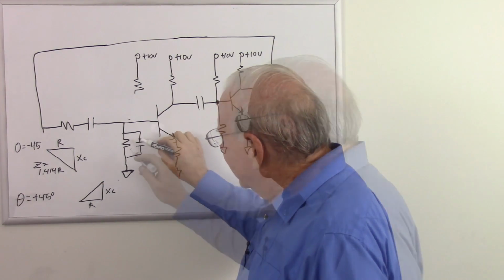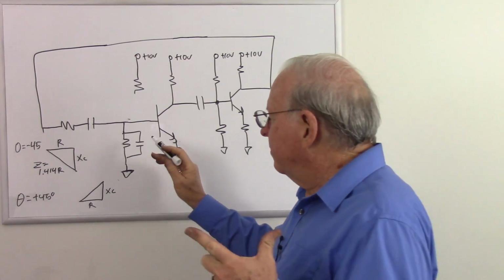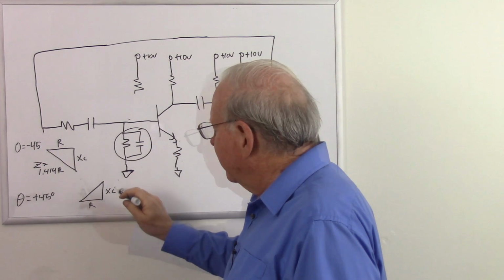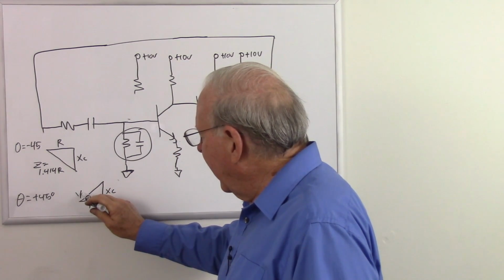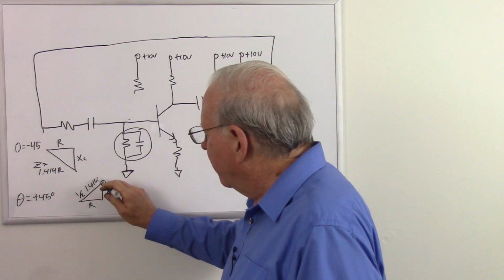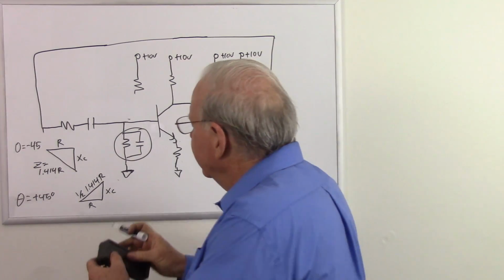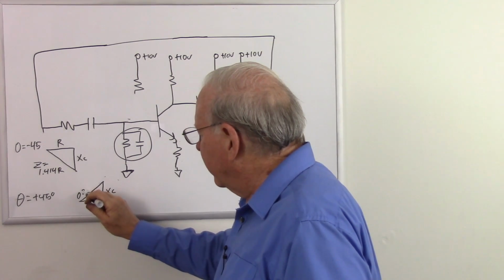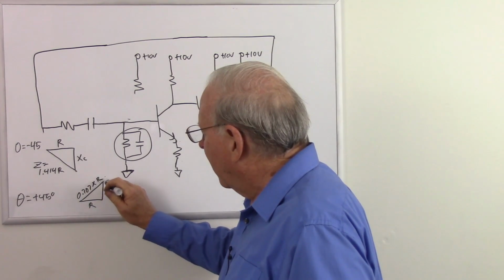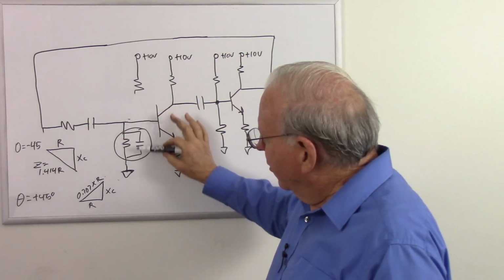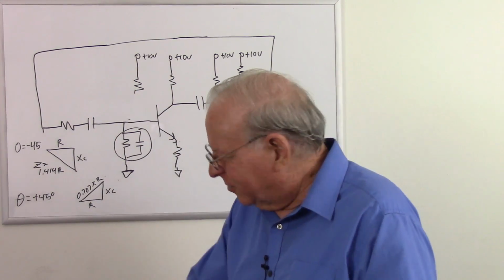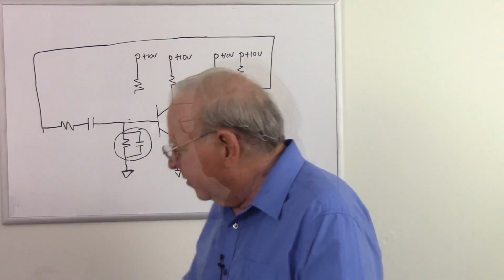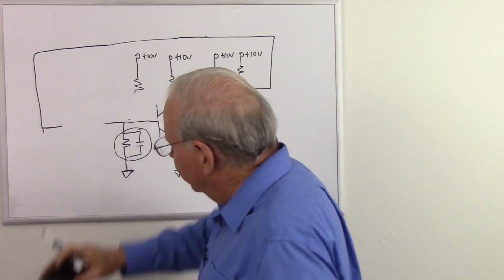But the result is, since these are equal, the product over sum formula works out such that the total reactance here is going to be 1/2 of 1.414 times R, or make it just a little simpler, 0.707 times R. And so the impedance here is going to be half the impedance there. So all of that talk just to say this, that because these are in parallel, they'll have half the impedance. So we'll just treat them like resistors now, just to simplify the circuit.